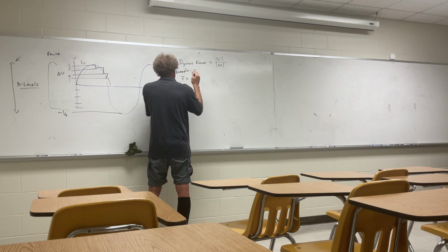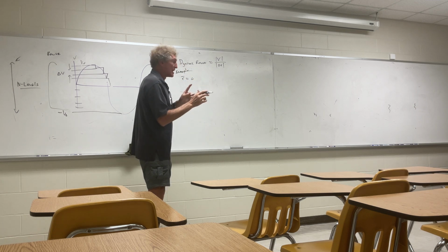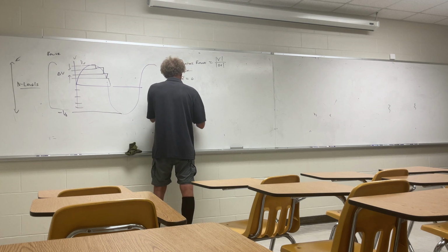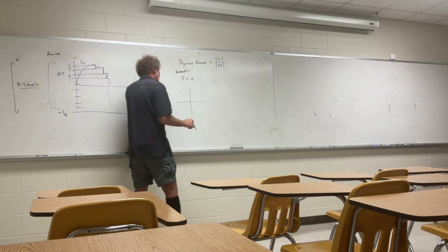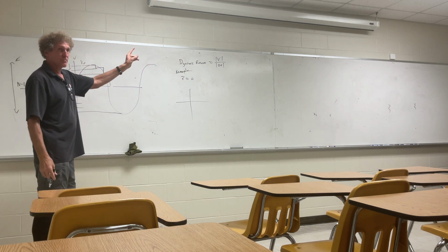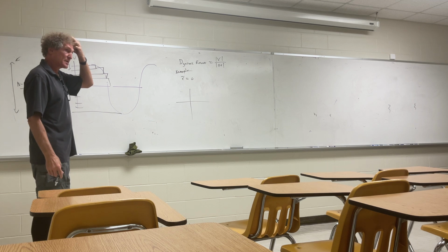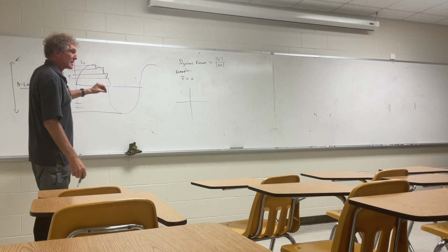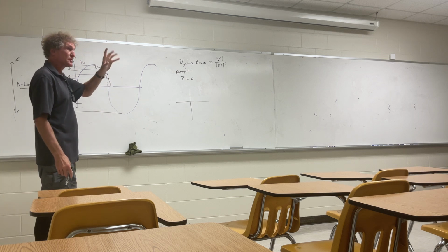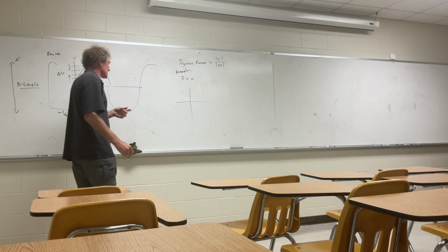It'll present the concept without making it too complicated. And I'm going to say if the mean is 0, there's also going to be a dynamic range. By the way, I didn't say this, but whenever they do this quantization bit for any kind of an analog signal, they assume the probability of the signal being at any point is the same. So it's going to be a uniform distribution.